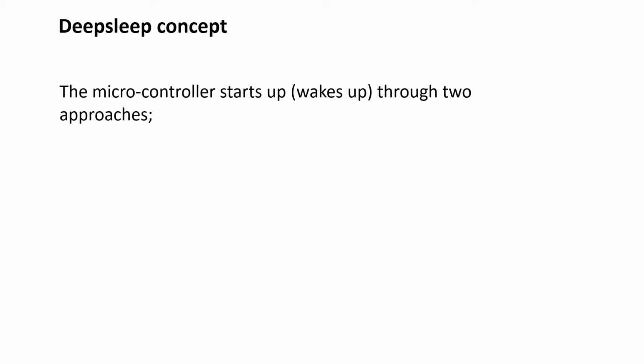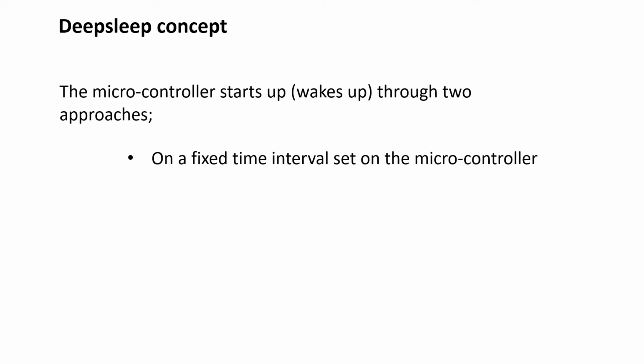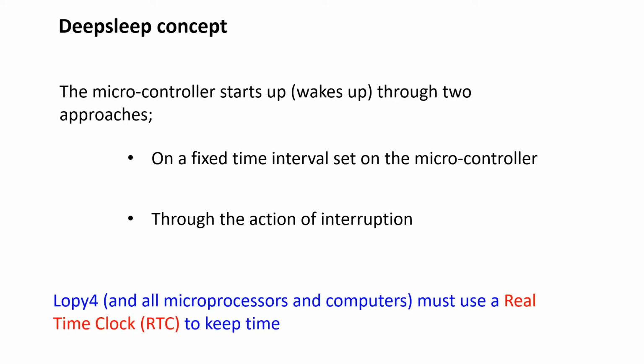The microcontroller is able to wake up or start through two approaches. The first one is on a fixed time interval set on the microcontroller, while the other one is through the action of an interruption. To implement these approaches, especially the first one, that is fixed time interval, the LoPy4 must use a real-time clock